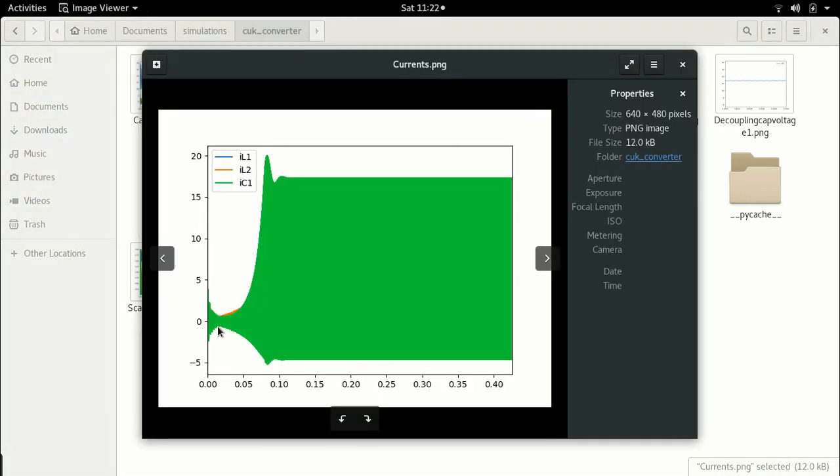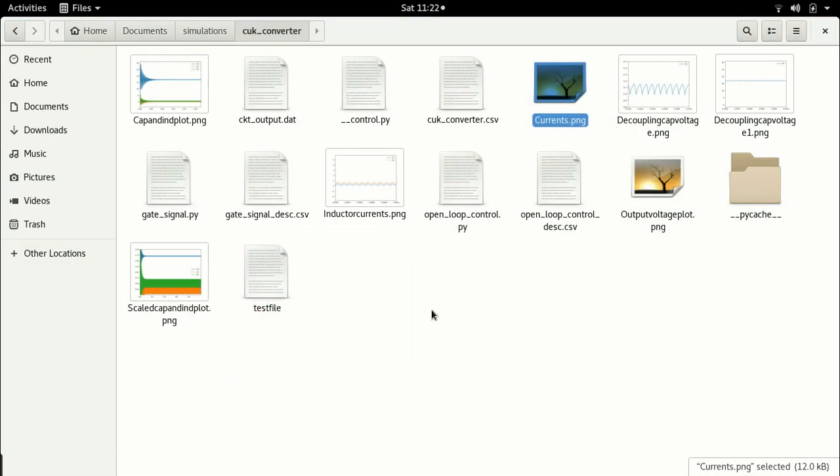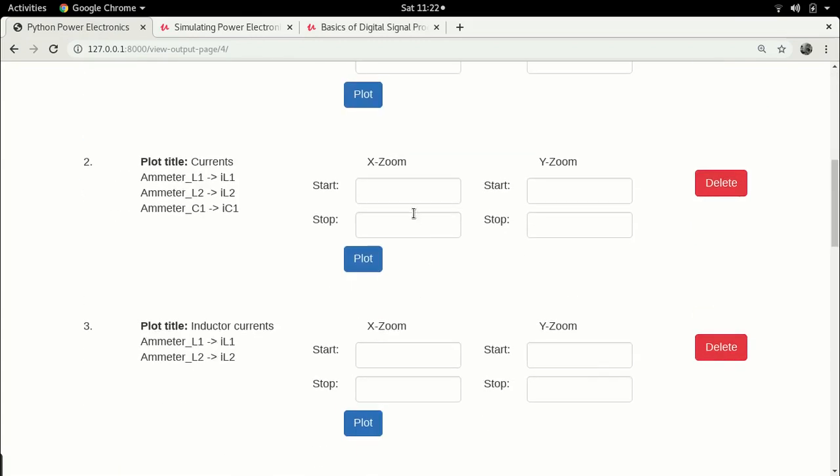So now we plotted it for this small range. Let's go and plot it somewhere where this transient is happening, because it's an interesting peak here. So we know that this should be around 0.8. So let's go and zoom in for 0.8 to 0.81. This is quite normal because you have to sort of investigate where the interesting part of your waveform is. And the only way to do that is to successively keep zooming in on a waveform.